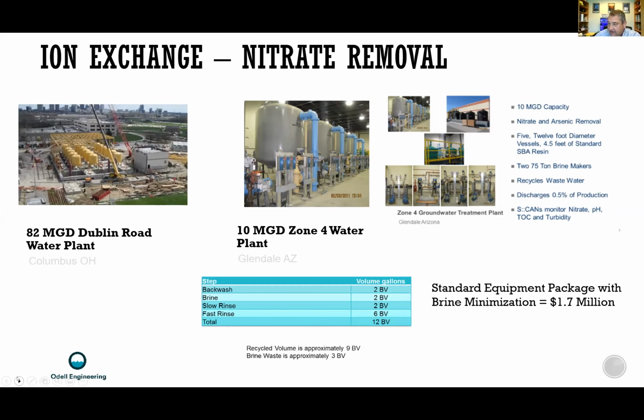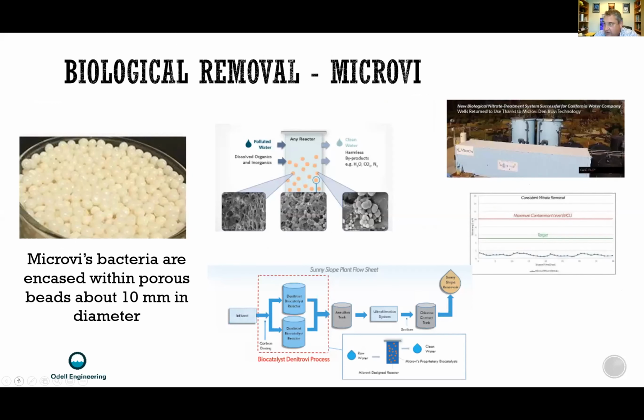There's definitely a lot of interest in biological removal. I've worked with one, this Microvi technology, that is really interesting. They have bacteria that goes in these encased porous beads, but the system itself isn't that costly. But you have to do quite a bit of post-treatment, and it's exposed to atmosphere, so you're repumping water.